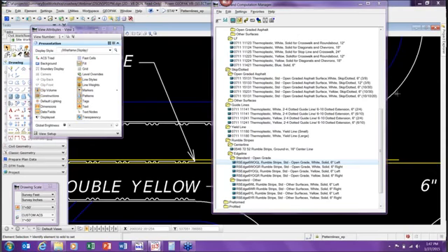Really quick, I'm going to see if there are any questions left that did not get answered. This one I don't know the answer to. Missy, is there a pay item for non-conflict removal? How was that handled? For non-conflicting pavement marking removal, if you're removing thermoplastic, it's paid under 711. If you're removing something like the profiled thermoplastic, the 701, then we'll pay for it under the removal of the 701, because you'd have a little more work required there.